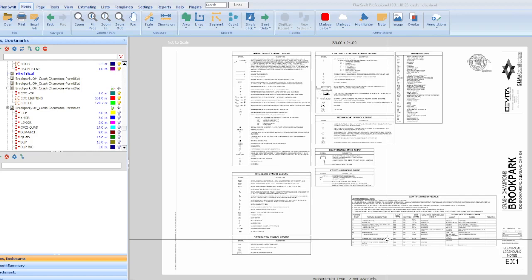For your single line diagram, it's pretty simple because the panels are where they are on the plan and they go to a particular other panel, so it's easy to be accurate with those totals. But when you're doing the wire and conduit totals, you're not going to get the exact same number as the electrician, or 10 electricians doing the same thing. What you want to do is make a good effort to represent the branch circuitry and the lighting based on the plans in the best way you can.